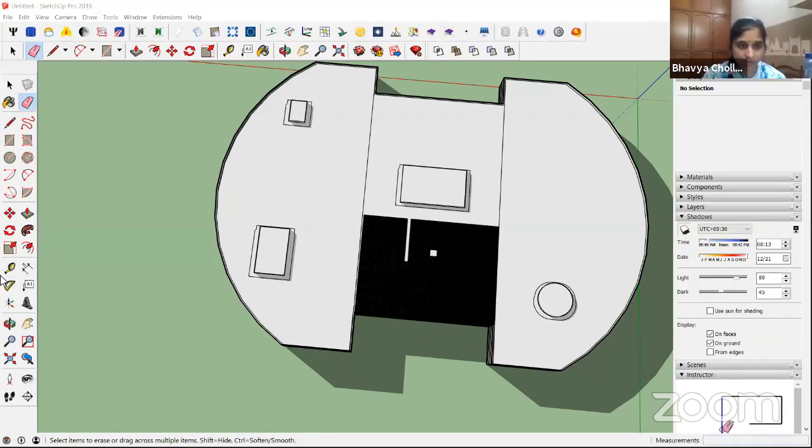Ma'am, how many modules are enough for a normal house or a small house? That depends upon your area, Vinith. Depending upon your locality and the obstacles present, you have to eliminate the shadow consideration, find the effective area where you can put the modules, and then design the module layout. Your investment budget is also important in deciding all these parameters. You have to do a complete detailed project design to understand how many modules are required.